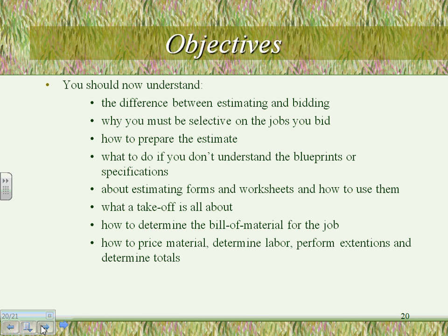Page 57, that's where it becomes a little bit awkward, this software that we're using, this Excel. Page 57, guys, takes the equipment and assigns a box and a cover to it. That's why I don't like it. It might be more complicated than it should be. When we go to a software, it's an assembly. When I take a switch, Spencer, in a real estimating software, the switch means what they call a switch assembly: the switch, the cover, and the box with it, and even the wire nuts that go with the switch. That's in a real good estimating software.